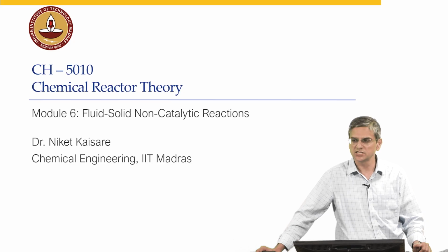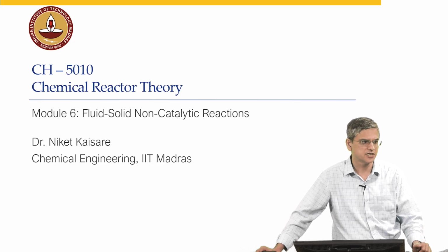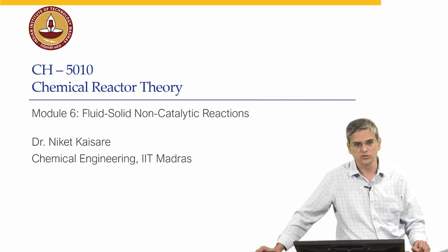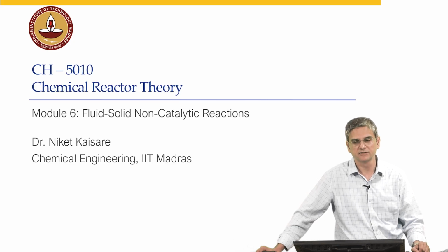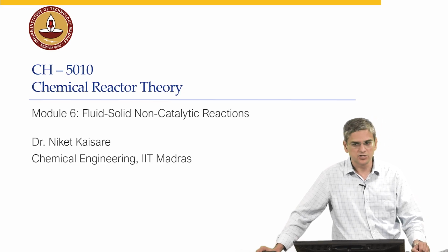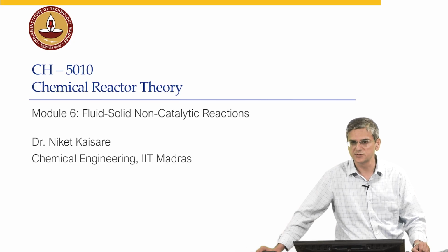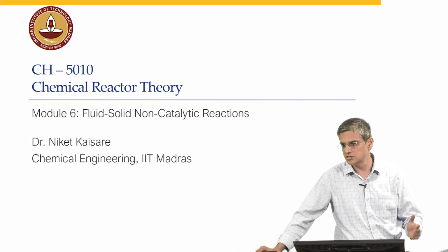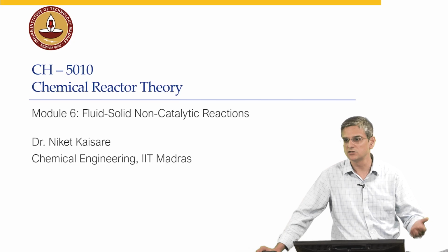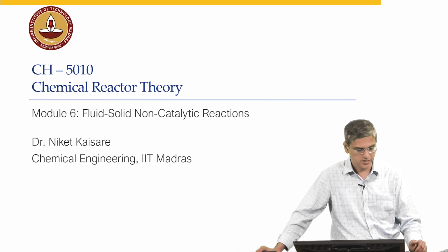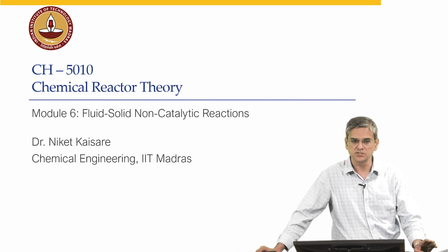There's one more type of reaction that's also an example of gas solid non-catalytic reaction, and that is basically if you have a catalyst pellet, what we have done in the previous module, and let's say that pellet has got deactivated. Now that deactivation could be because of coke formation, it could be because of some deposition of some other species and so on. So if you have a catalyst pellet where coking has happened, then the removal of coke or decoking is also another example of a non-catalytic reaction. So these are various examples, and we'll look at how to handle these types of systems.